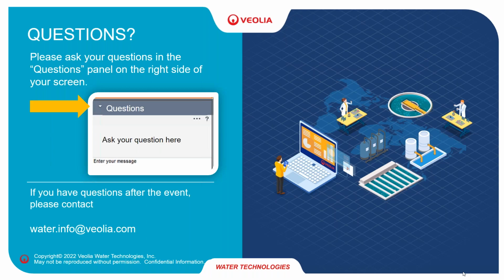Yep. Okay. So upstream of the filter, the requirement is a primary clarifier. Not that solids themselves, in terms of concentrations, are so much of an issue, especially for diluted water. But experience showed that if you don't have this primary clarifier, you'll end up with surface clogging of the filtration bed. That's probably linked with toilet paper and fibers from the wastewater. The primary clarifier will remove this fibrous material and allow the TSS to penetrate deeper into the media filtration bed.